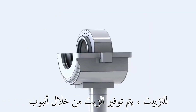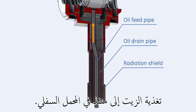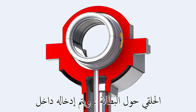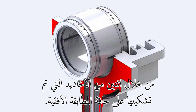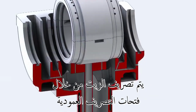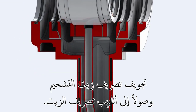For lubrication, oil is supplied through the oil feed pipe to a port in the lower bearing housing, where oil fills the annular space around the liner and is admitted inside the liner through 2 grooves machined at the horizontal matching edge. Oil deflectors are mounted on both ends of the liner to help containing oil inside the liner. Oil is drained through the vertical drain slots at the bottom of the lower liner half to the lube oil drain cavity down to the oil drain piping.